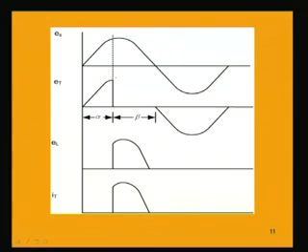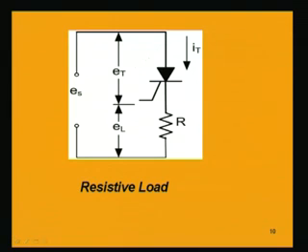The conducting voltage or the voltage after turning the thyristor on is 0, that is why it will be dropped down to 0. It will drop down to 0 and be 0 till the point when the input voltage becomes negative, because you know that the thyristor is turned off if the anode is made negative with respect to the cathode. So, in this circuit the voltage ES is a sinusoidal voltage like this. So, this is positive half cycle, this is negative half cycle.